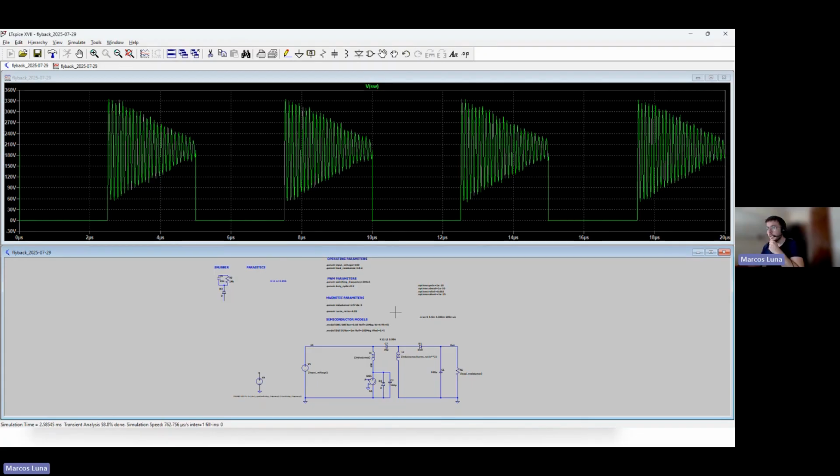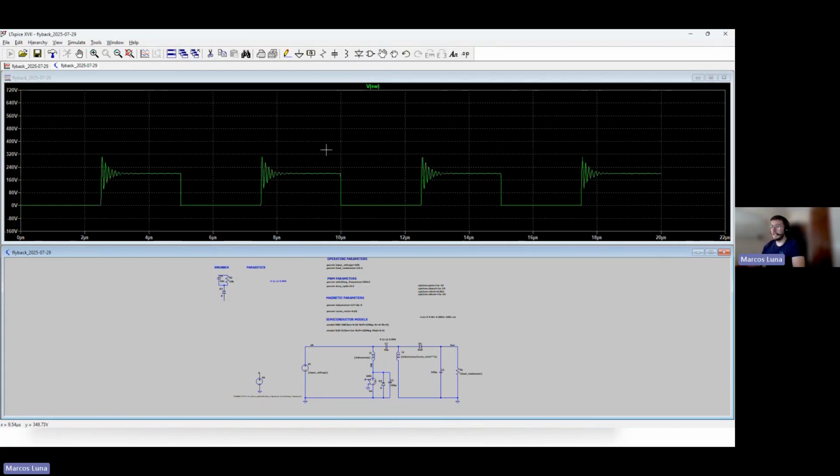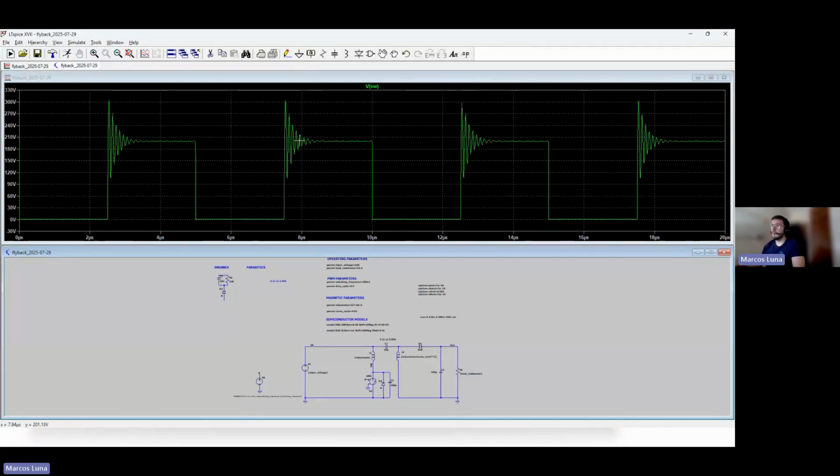And what you will see is a damping in the signal, and this is something you probably find more familiar. You still have oscillation, but then you have the waveform. So as you can see, it's very important to account for every parasitic, because you can also add here the intra-winding capacitance and the capacitance of the diode that affects this part. But typically, in most cases, the COSS of the MOSFET is the one that dominates this oscillation, and also the leakage inductance of the transformer.